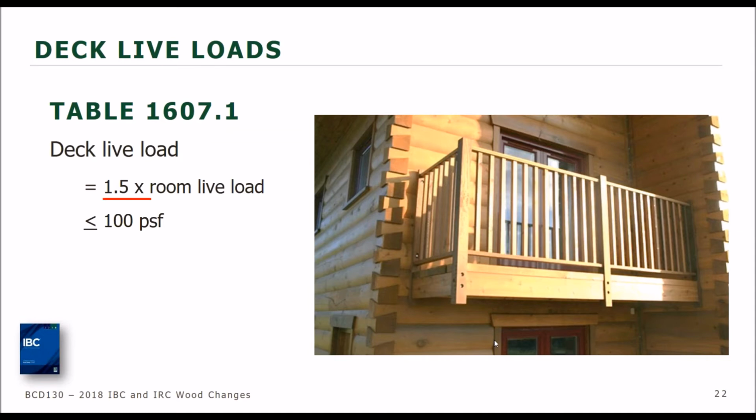But it is capped at 100 pounds per square foot for both the IBC and for ASCE 7, because that's an assembly occupancy. And at that point, the number of people in a room is quite high, so you're allowed to have a very dense population in there, same as the deck, and therefore they cap it at that 100.